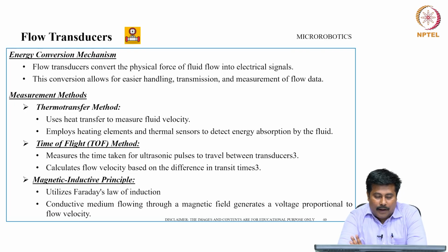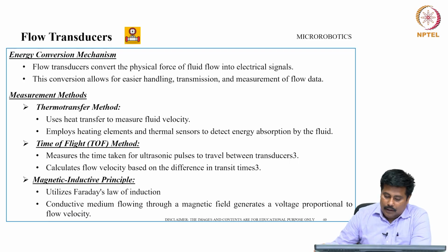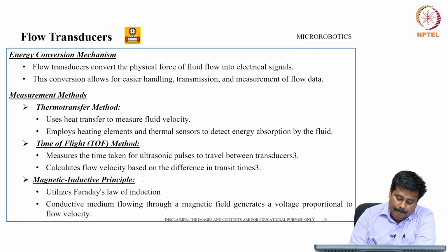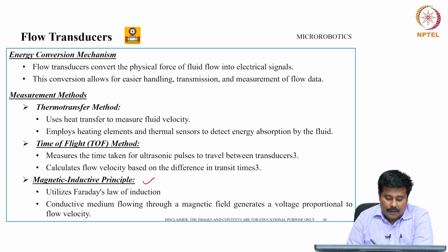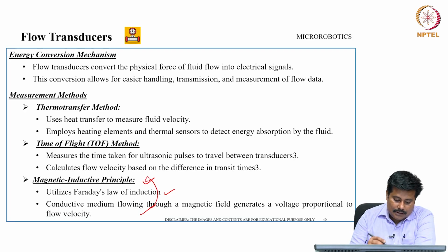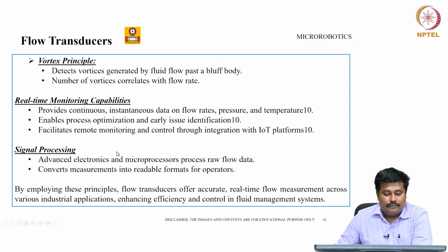Next, the time of flight method measures the time taken for ultrasonic pulses to travel between the transducers. It calculates the flow velocity based on the difference in transit times. And there is one more configuration, called the magnetic inductive principle. This principle utilizes Faraday's law of induction. A conductive medium flowing through a magnetic field generates a voltage proportional to the flow velocity, which is what the magnetic inductive principle represents.